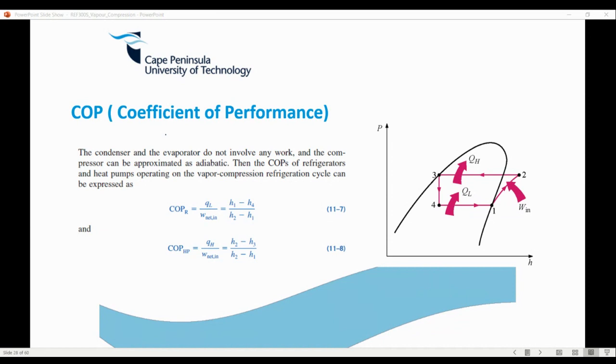No, a heat pump is a completely different device. It's actually one of the most efficient water heating systems. Instead of your condenser rejecting heat, we use the heat rejected to either heat the room or heat water. In fact, my research is based on a heat pump, particularly a solar assisted heat pump. Instead of using a boiler to produce heat, a heat pump is a very efficient device.